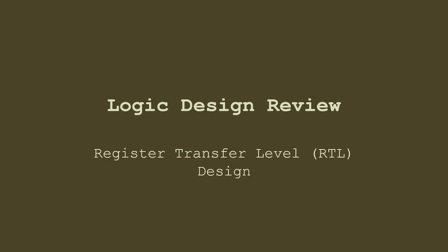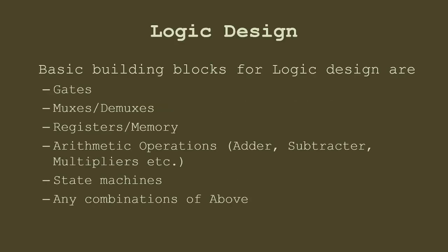Okay, so normally we use this term register transfer level, or RTL, in multiple meanings. One meaning is that when we say that we have an RTL level diagram of a design. Another thing is that when we say that RTL is ready, then normally what we mean is that we have already written the Verilog code or tested it. So Verilog or VHDL are two popular languages. We'll only be covering Verilog in this section.